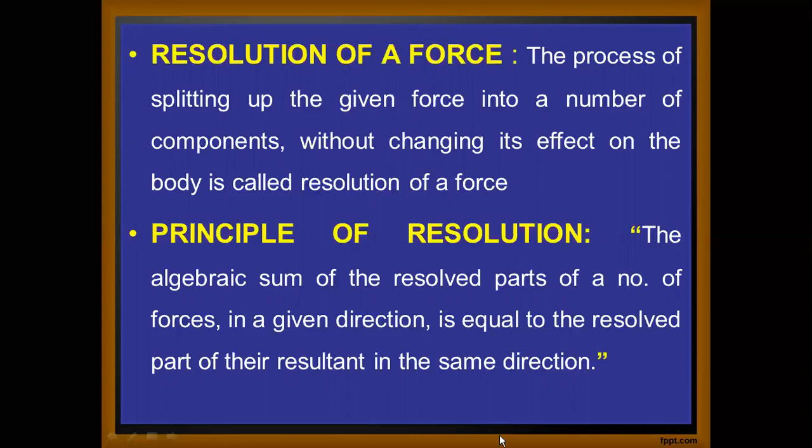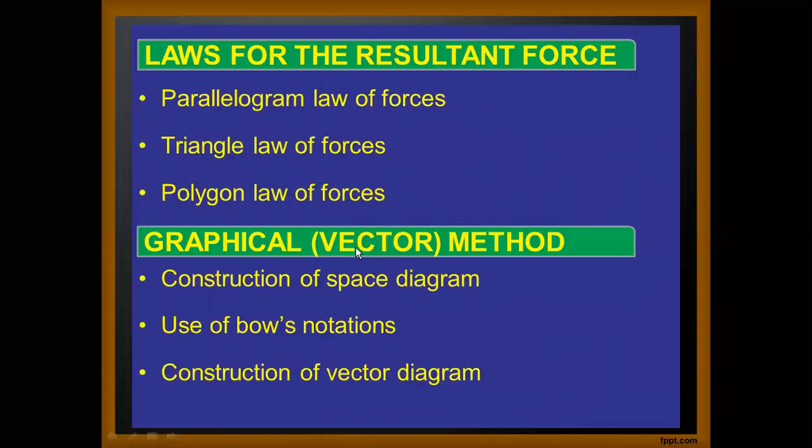What is the main principle involved while resolving the force? It states that the algebraic sum of all the resolved parts of a number of forces in a given direction is equal to the resolved part of their resultant in the same direction. That is, if you split up a force acting along one direction, the net effect caused by the single force and the net effect caused by both of its components should be the same. That is called the principle of resolution.